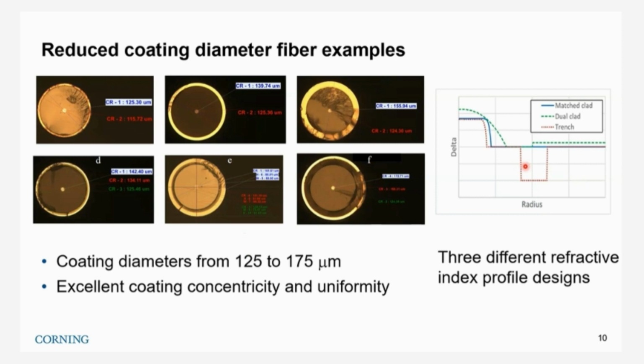For the profile design, we use three types of profiles. One is the simple step index design, and the second type is dual cladding. We have a slightly lower inner cladding and raise the outer cladding, and the third type is the trench assisted profile design.